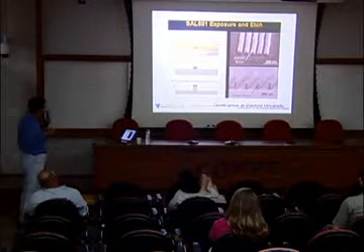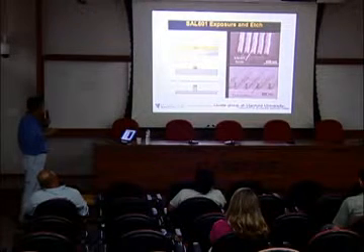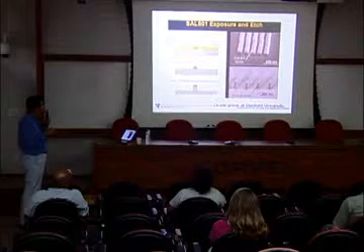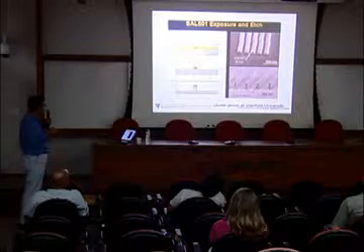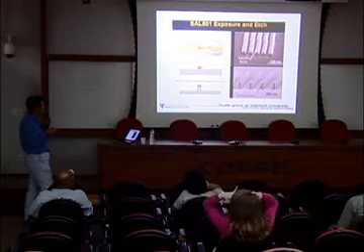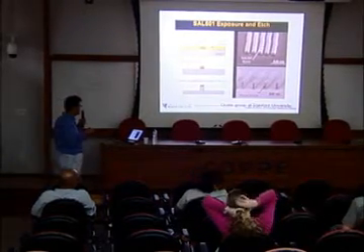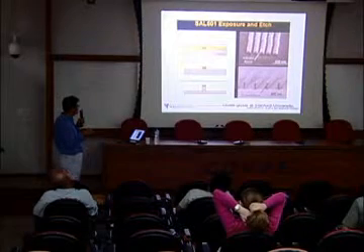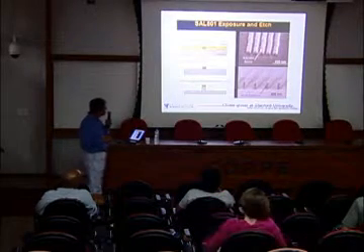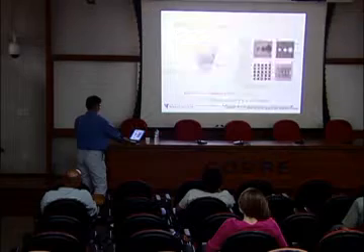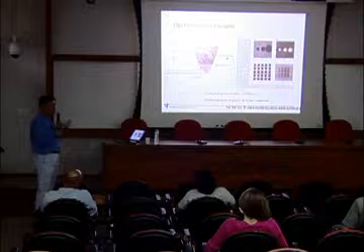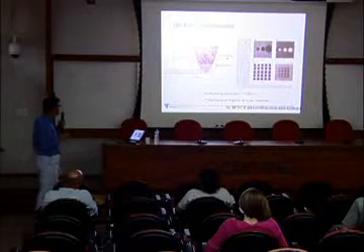So if you see the structure, the fabrication method, then using the tip, we can transfer the electrons, then that will be exposed into this polymer layer. Then a hardened layer will be left, and then the other layer will be etched out. Using this one as a mask, then we can etch out more of the silicon. Then these are the silicon structures that are fabricated using this method. And this one is another kind of a branch method of SPM lithography.